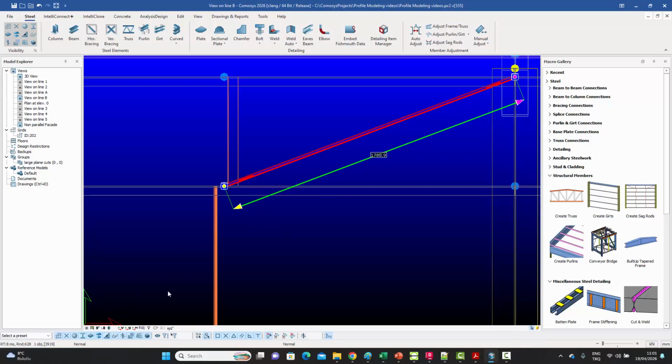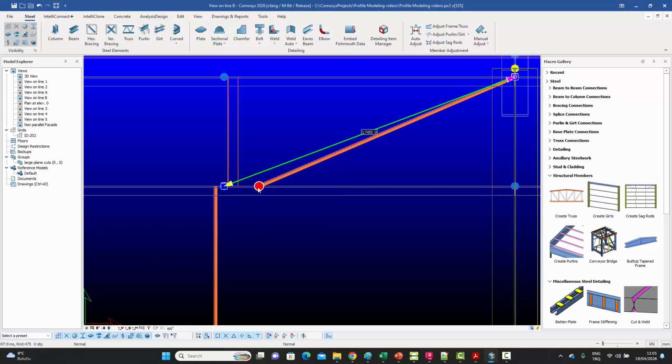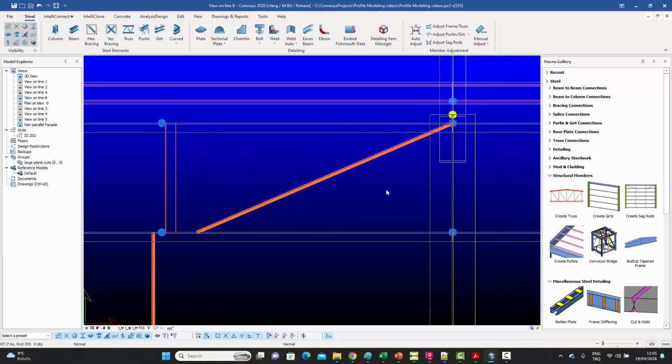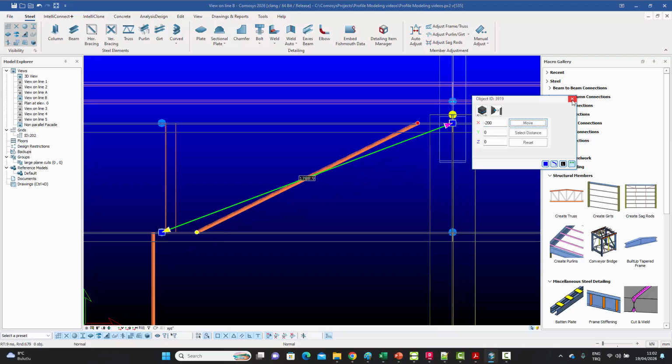This is the X direction, so we click on this blob over here, and we say 200 in the X direction, say move, and that will basically move the working point. Physically, it'll still be there as far as the line mode is concerned, but it'll be offsetted, and we can do the same for the top over here. I'll give it an offset of -200, like that.